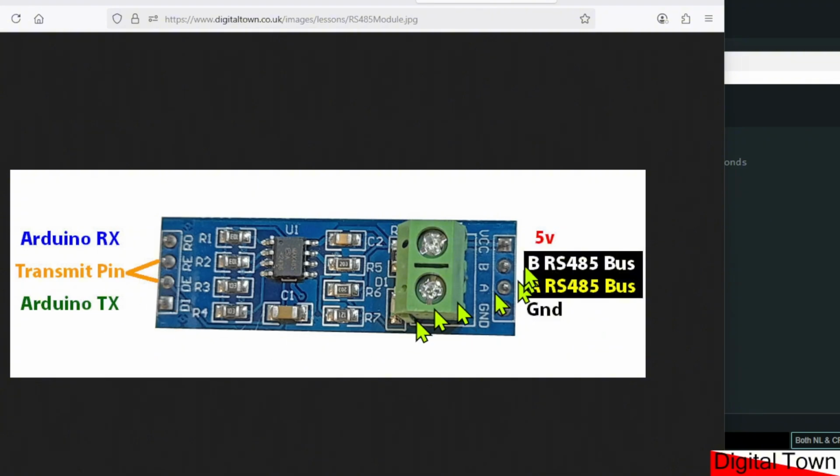I then have 5 volts that is going to the VCC. Obviously ground, this is the ground of the Arduino. And then I have a B and an A. And these are these two wires. I've got one white wire in my diagram and a yellow wire also for the opposite. And these are the ones that are dealing with the signal.